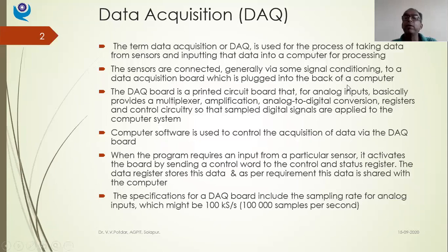As I said, on the motherboard of the computer, we have this data input slot. In that slot, this DAQ card or data acquisition card is inserted, and thereafter that data is taken for further processing. The DAQ board is a printed circuit board for analog inputs. Basically, it provides a multiplexer, an amplifier, an analog to digital converter, then registers for storage of data, and then control circuitry so that sampled digital signals are applied to the computer system.